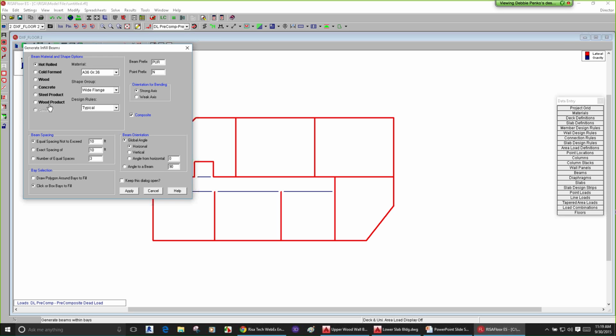Now, infill framing, you have some decision. You can use some wood products instead of just glue lam. You have things like I-Joists. So you have a laundry list of different I-Joists that we've had for different manufacturers. I'm just going to go with the standard APA I-Joist. And you'll see here, we actually added Canadian in there as well. But I'm going to go ahead with the standard APA I-Joist. It's just our generic I-Joist if you're not familiar with it.